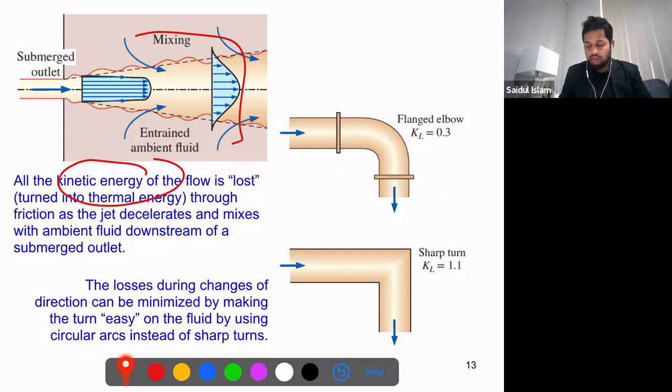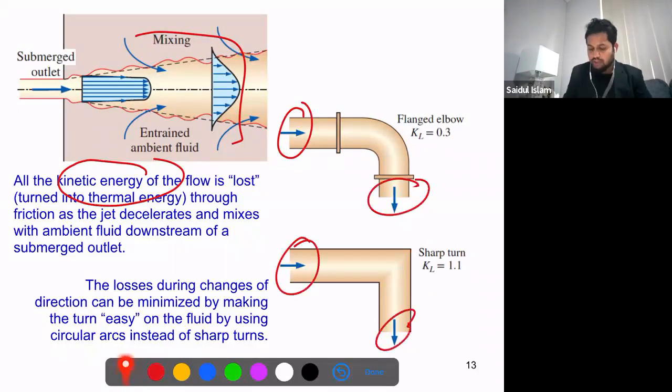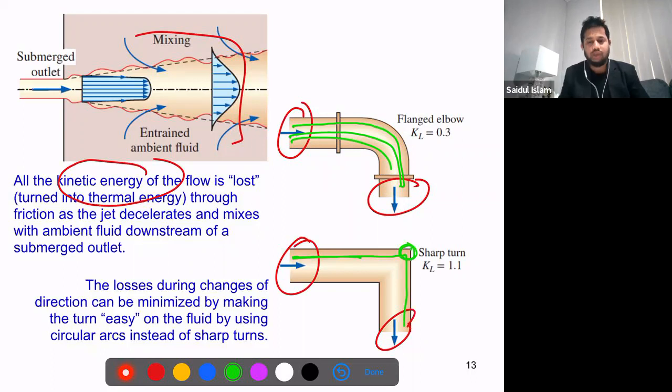And now this is one thing. So far we were talking about this inlet and the outlets. What will happen in the middle, like the elbows? You can see when it is making a sharp turn, the loss coefficient is significantly higher than for the smooth turn, for the same reason. The fluid can easily make a turn like this, but here it will be kind of like this. So we'll get some sort of stagnation in these sections. If you look at some saved results, you can observe the contours where we have zero velocity.